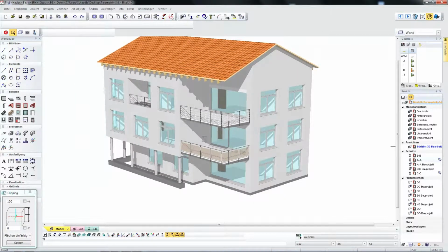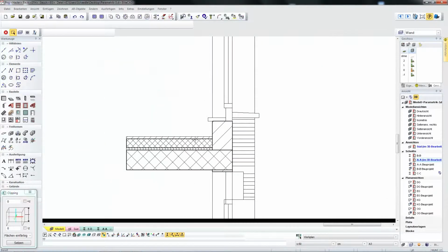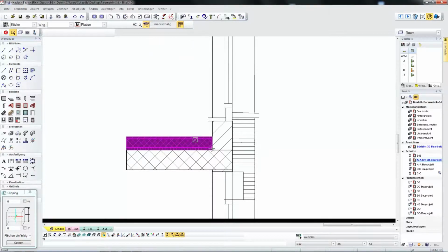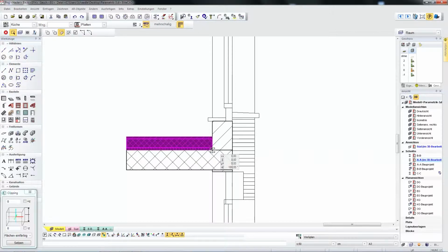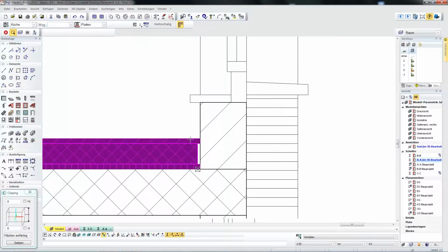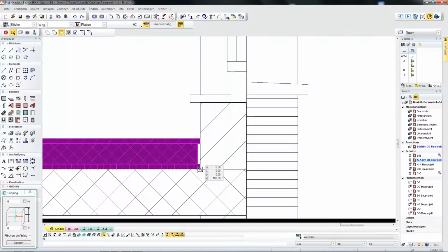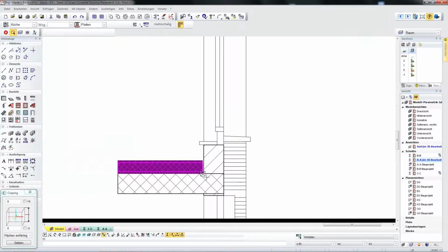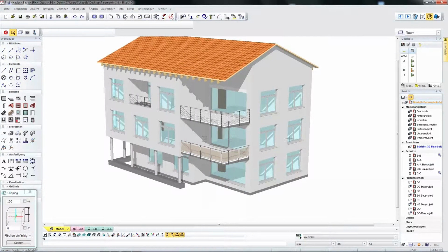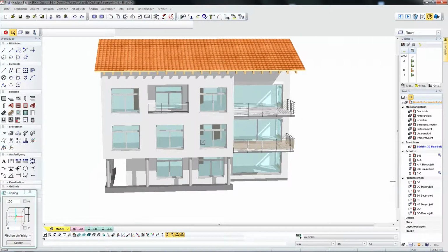The parameter settings are very wide-ranging. Slabs can be inclined, or the edging strips of a subfloor modified. Each individual layer can be modified. Here, for example, I correct the subfloor, the concrete, and then the entire timber construction on top, i.e. the parquet flooring, also using handles. These detailed parameter settings enable 3D planning of your building as far as the work drawing stage, and for the building to be represented in plans accordingly.